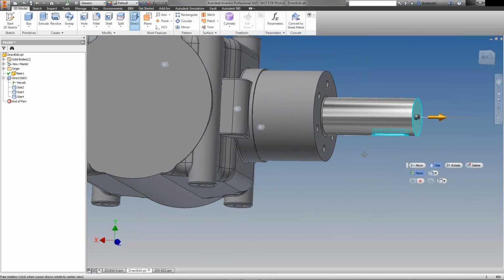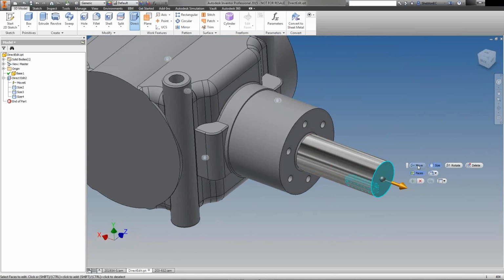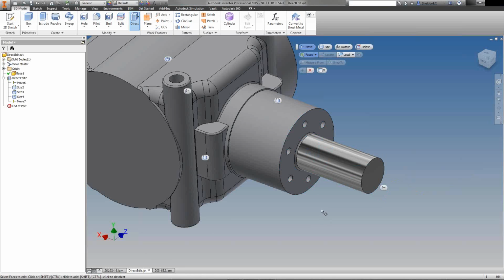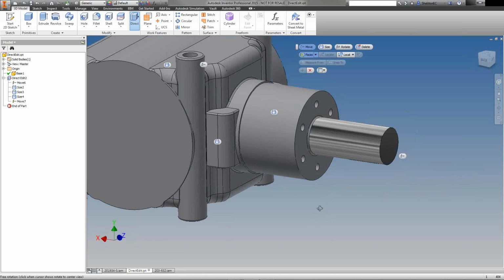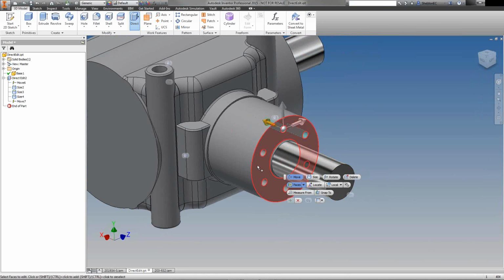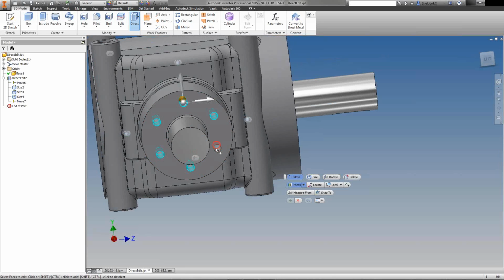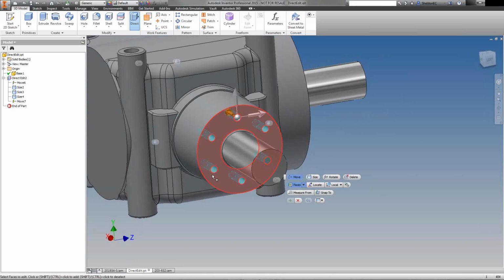Okay, I'm going to change the length of my key and the shaft. We'll move that relative to this face, and we'll make it say 54. Okay, pulling that in. And maybe changing the rotation of the hole pattern that I've got in this block. On the face there. Okay, I'm going to rotate that.